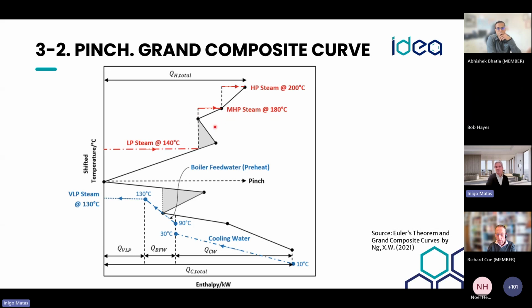So why is this so relevant for heat pumps? Because, as we will see later, the COP, as Avi mentioned in the previous webinar as well, is very related to the lift. So we will always try to avoid lifting too much energy, because that's going to result in a smaller COP. So again, the pinch is very good at helping us identify what the actual temperatures required for each of the energy packages are.